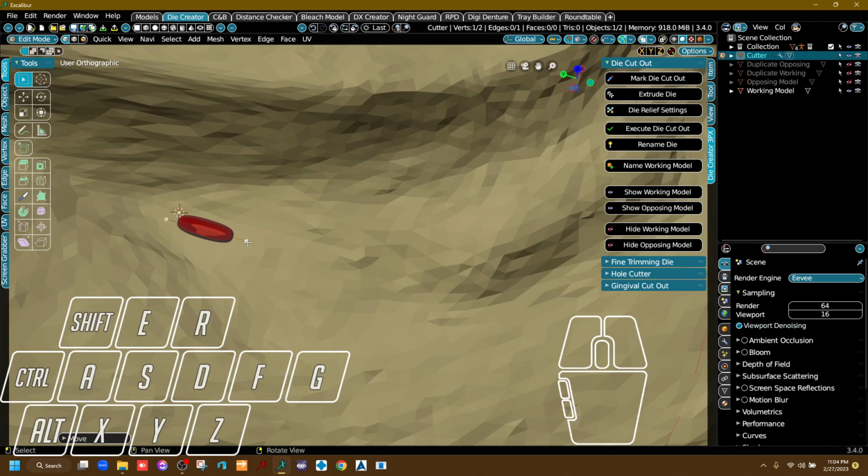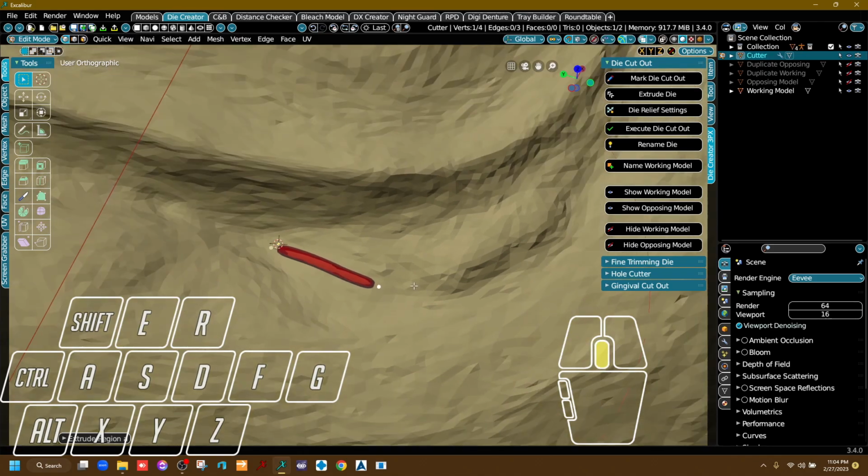So when I have this point highlighted and I press E, it's going to add an additional point at my cursor right here. See, so I still have that old point right there. It's tucked underneath the red line. But now I've got this thing following my cursor. Again, I haven't clicked. I just pressed E once, and that extruded the line to this point. So now I'm just going to click to place it, and I'm going to extrude again and place it.